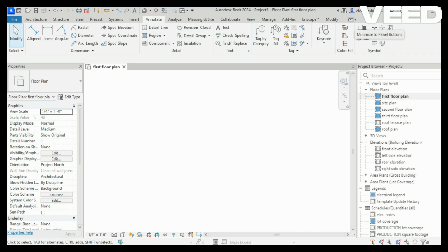The way it works is we'll go through each tab as we draw the model. That's the best way to learn. And plus, it will provide some repetition for you, as when you're drawing walls, you'll draw more than once, okay? So first things first, let's go ahead and draw the architectural walls, okay? And what we're going to cover today is architectural walls. We're going to show you guys how to use the selection box, the mirroring function, the create similar function, and the start and end radius arc function when drawing walls.